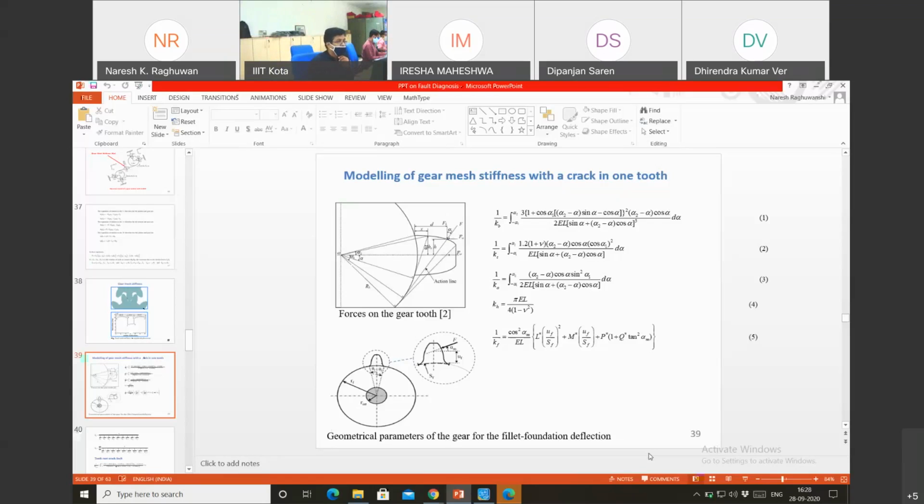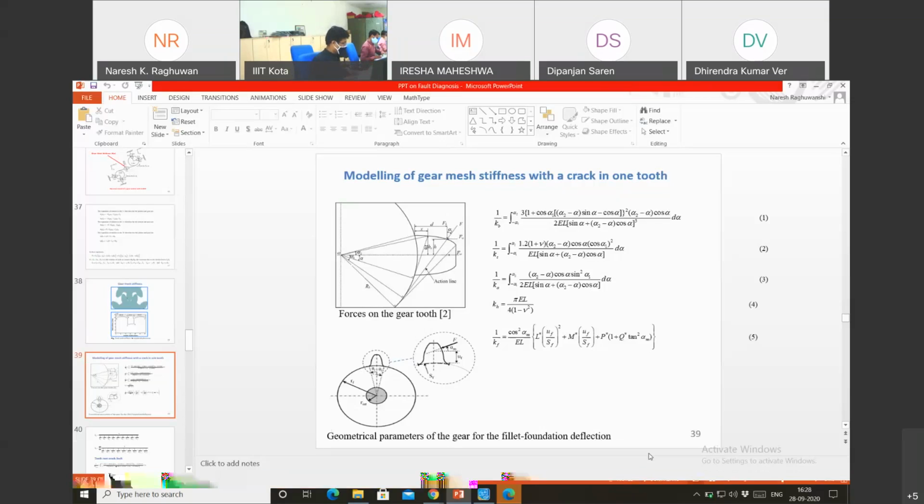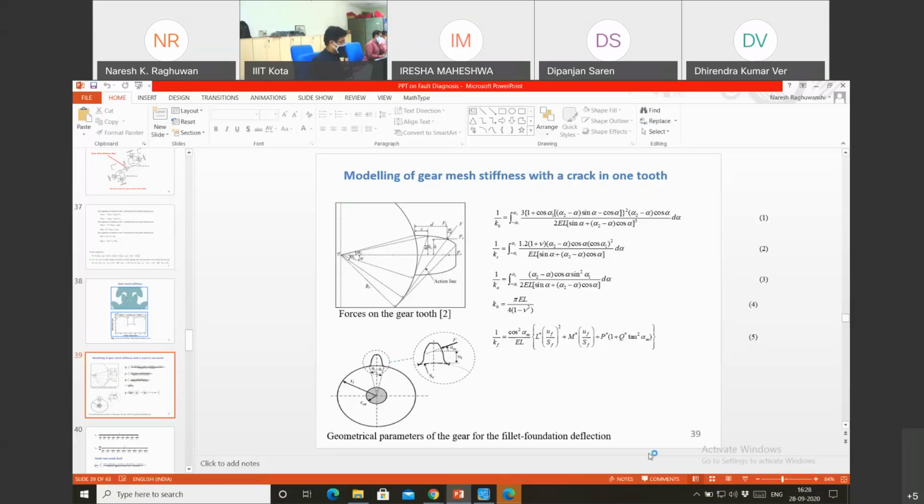It is a design modification I have seen in the literature. Where we fix the base of the cantilever, just below that fixed edge, we provide some hole or ellipse kind of cavity throughout the thickness of the gear disc. It is kind of a tunnel structure just below the gear tooth. Actually, if you insert some hole, then in actual practice there is a gear with some hole or cavity in the body.